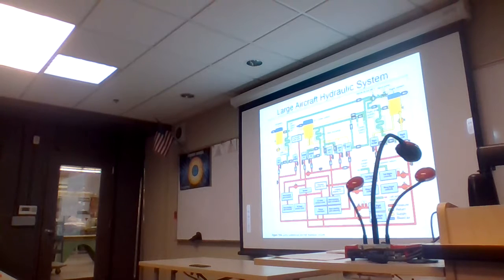On a lot of Boeing aircraft, they have a combination of electrically driven pumps that they call ACMPs, alternating current motor pumps. They also have engine-driven pumps, EDPs, that they provide fluid to. The pumps really don't create pressure. The sole purpose of really any pump is just to provide flow. You'd have to trap that flow in order to create pressure. A lot of folks just refer to the pump as the pressure producer, but it's not. It's just a method of creating flow.